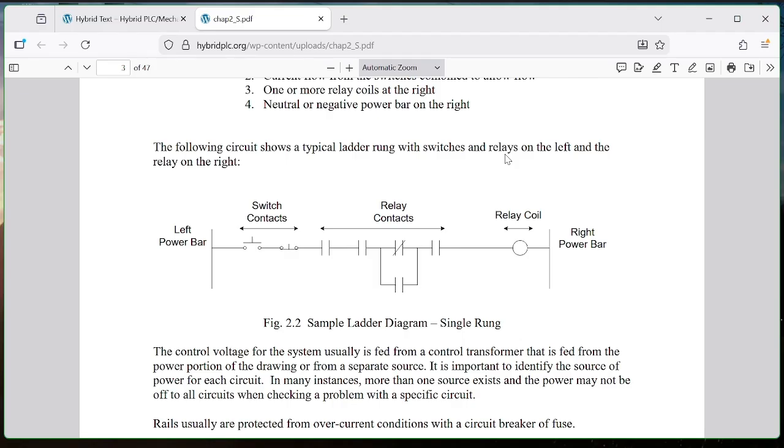This is the kind of relay that I heard when I first walked into industry. These are the big boys, they clunk really loud. Okay, this would be a regular relay, the big old style relays. The ones that were coming around before are a little smaller. These are NEMA, those are IEC, or this is the American style, that's the European style. They shrink everything down because they're more economical and they do everything smaller. But basically, you get the same bang for your buck with this as you do with that. It's a little bit beefier, but they do the same thing.